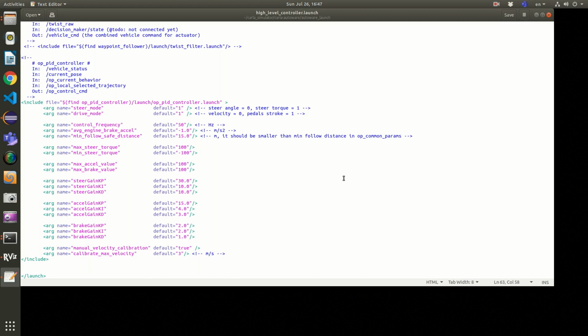This is a simple PID, so don't expect really good smoothness all the time. You need a feed forward PID, and you also need to activate maybe a high frequency blocker filter to filter the unwanted steering frequency, so you don't have your steering shaking in front of the driver. I think that's all.